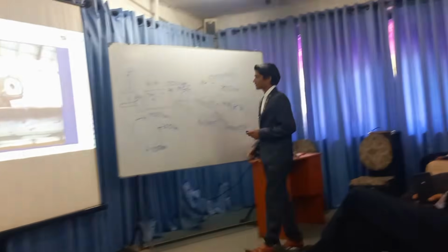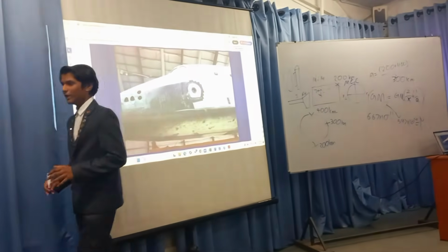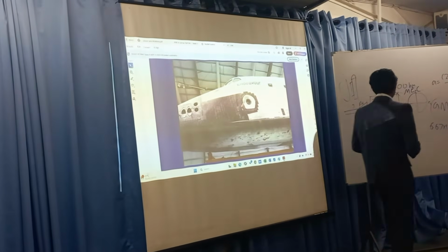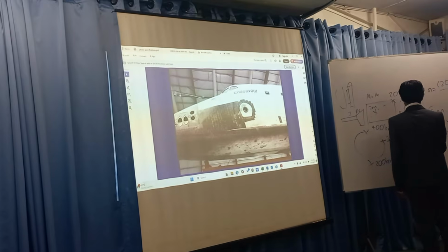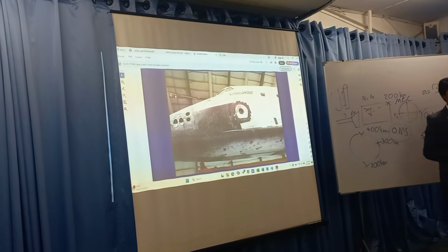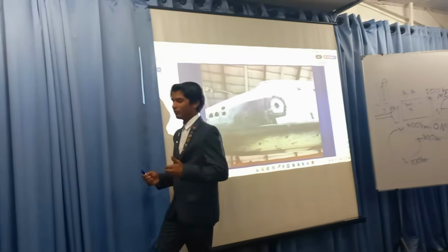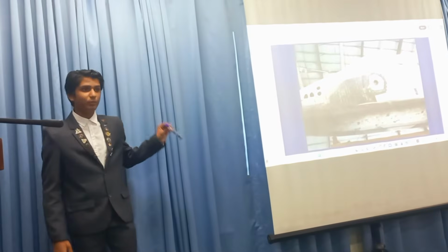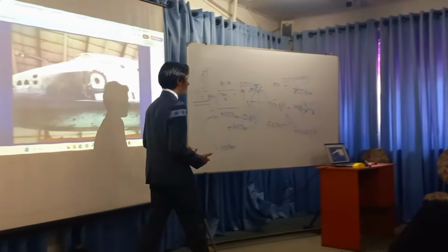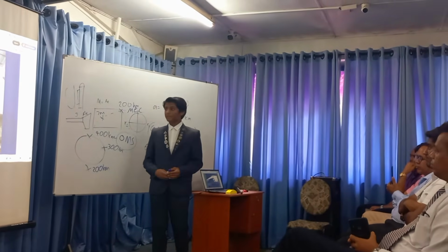Now, after we reach 200 or 300 kilometers at apogee, the space shuttle will have to rely on its OMS system. OMS stands for Orbital Maneuvering System. It runs on monomethyl hydrazine, and also on nitrogen tetroxide as the oxidizer, and it's responsible for circularizing the spacecraft. What I mean by circularizing is the point where the apoapsis and periapsis are about the same. This is what circularization is. Sometimes the orbit can reach about 100 kilometers of difference between the periapsis and apoapsis, but that's highly unlikely.